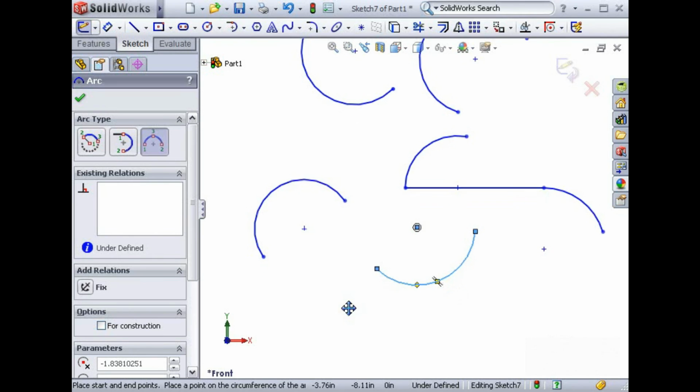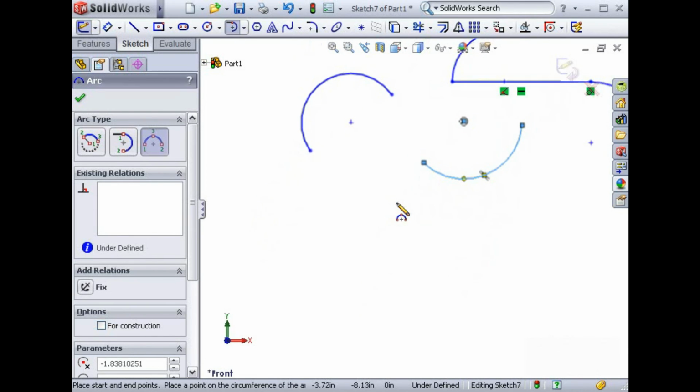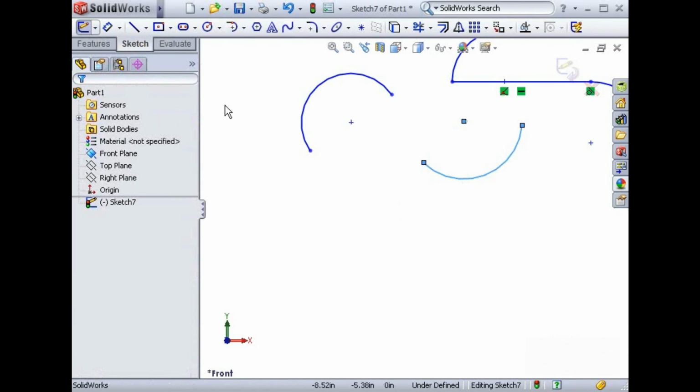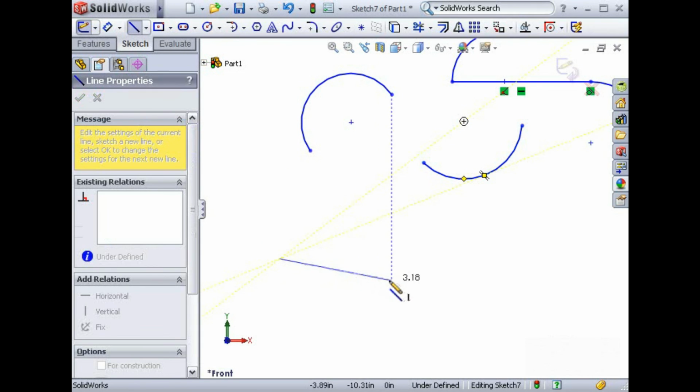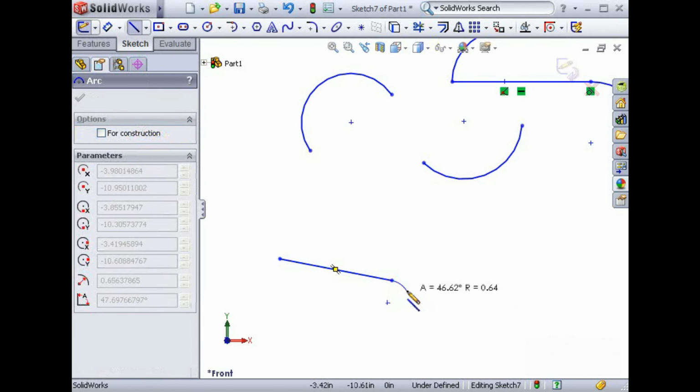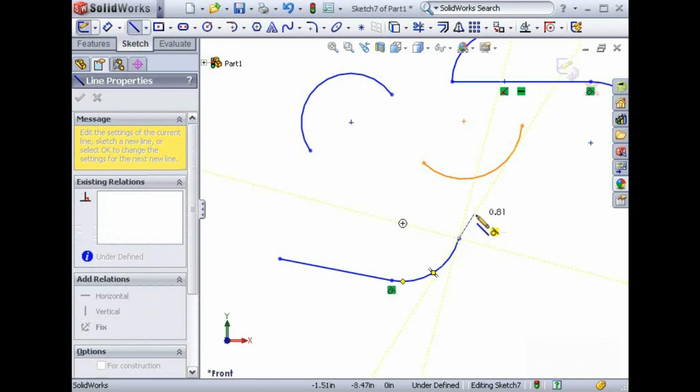There is one additional and very useful method to create an arc that does not appear on the Sketch toolbar. It's called Sketch Auto Transition and is accessed from the Line tool. Begin a sketch line, and to switch to an arc, simply move your cursor back to the beginning of the line segment, and move your cursor off in the direction you would like the arc to continue. Notice the Line tool has switched to an arc. You can control the direction of the arc by moving your mouse in different directions from the starting point. After completing the arc, the Sketch Line tool is reactivated.